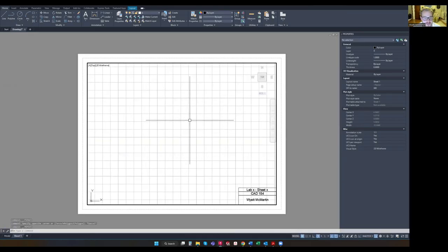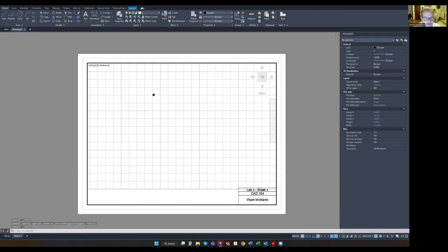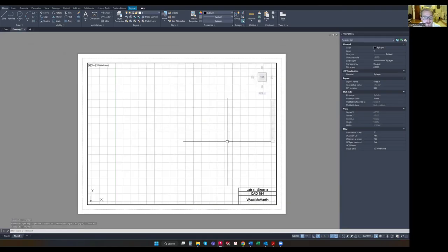When you double click inside your viewport, you're only panning the model space that we're looking at inside the viewport. So that's what the viewport does. The viewport allows you to see into model space. So we're going to draw in model space, and then you're going to plot it inside the viewport in Paperspace. And that's going to make a lot of sense.